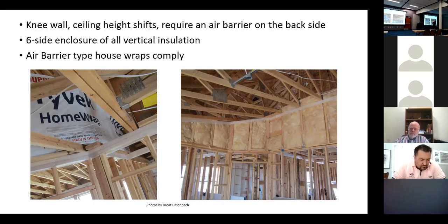I guess it's related to attic insulation. So in some instances where you have a roof joist and you just fill them up to within 1 inch of the underside of the roof deck, even in the slope conditions, you're not really required to ventilate once you've filled it. But you're going to have that convection. Is the reason that that's not required in the code because you've got the heat load on the roof and it just diffuses the moisture?